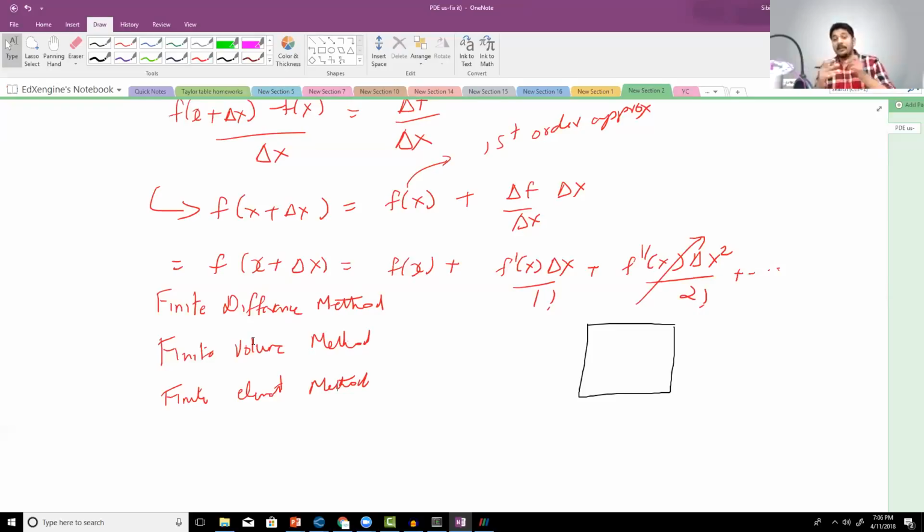When you solve that matrix, you get your values for velocity, pressure, temperature, from which you can calculate shear stress, from which you can calculate your drag coefficient. Okay, so that is basically a 101 of CFD.